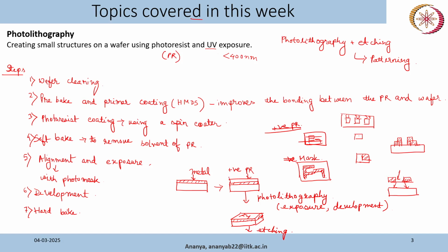Okay, so after that, I'll only make the top view of it. You will have this kind of structure. There will be photoresist and there will be metal below. Now you will remove the photoresist layer by using acetone, and you will be left with the metal electrodes, metal interdigitated electrodes like this.